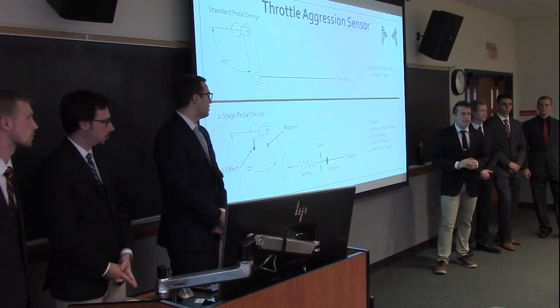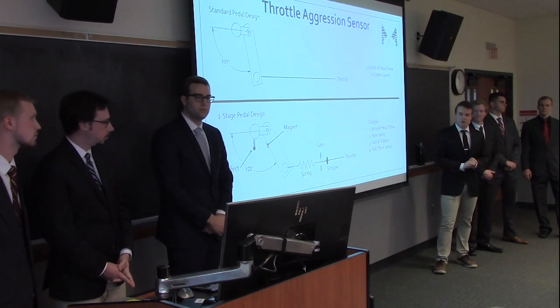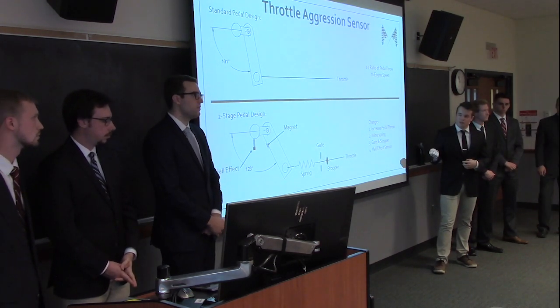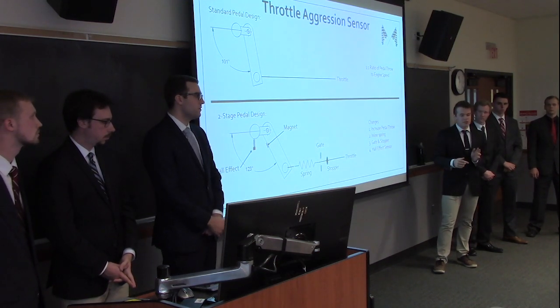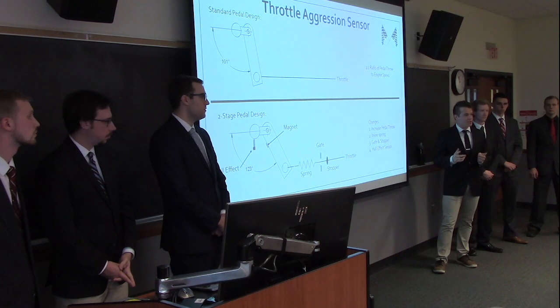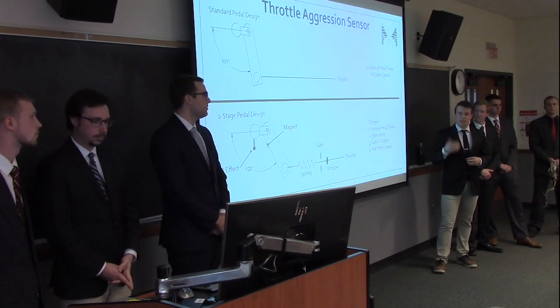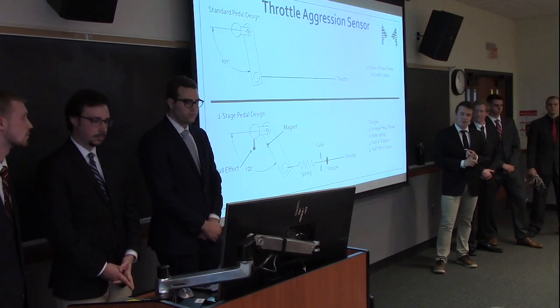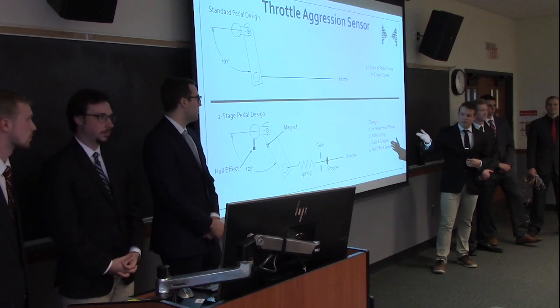On most modern day cars, there are settings called eco mode and sport mode. And for those settings, they do a handful of different things with the engine, transmission, suspension. But as far as the transmission goes, if you're in eco mode for a car, it actually shifts the transmission sooner so you don't over rev the engine, giving you less torque, less acceleration, but better fuel economy. In sport mode, it actually shifts the transmission quicker, giving you more acceleration, a higher torque, and a worse fuel economy. So that is why we implemented this for the car.